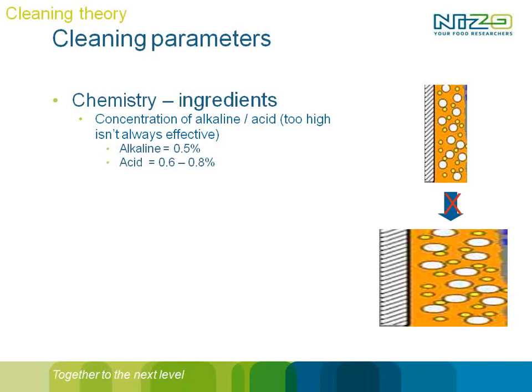Looking at lab conditions, normally an alkaline concentration of 0.5% is enough, but we do see in practice that 1% is normally applied, with very good results. Looking at acid, you see 0.6 to 0.8% applied in industry, doing the job very well.